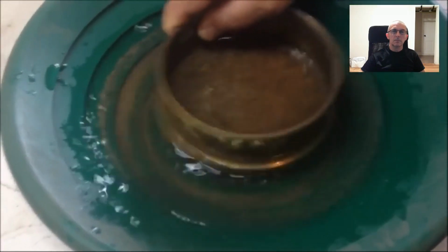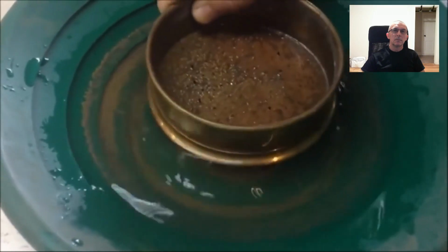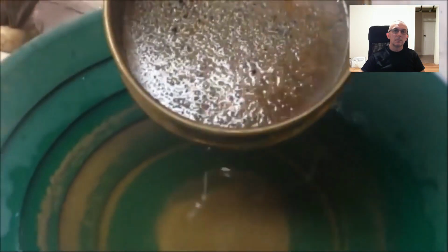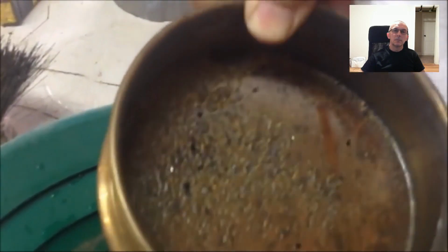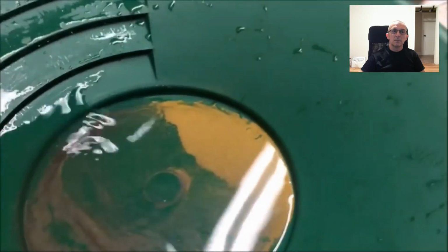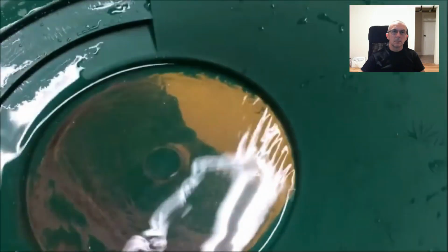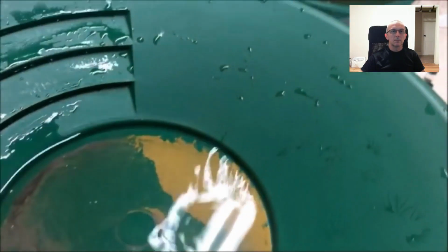We're taking the gold we recovered off the table and we're going to screen it into 3 different size fractions. This is the 100 mesh screen. It's a little bit hard to see in the glare, but there's the gold on top of a 100 mesh screen. And there's the gold that went through a 100 mesh screen. Now this is all the material that went through a 325 mesh screen. And we've got it fanned out pretty well, but you can see how fine it is. So there's that 325 minus.